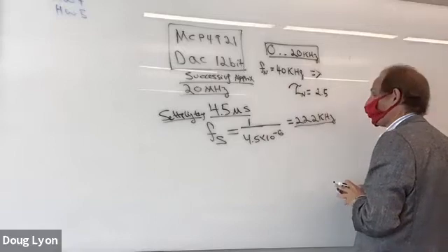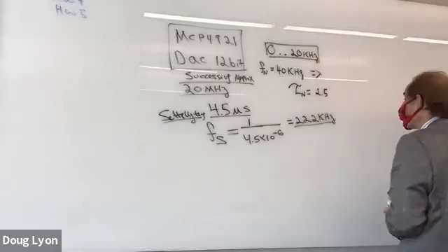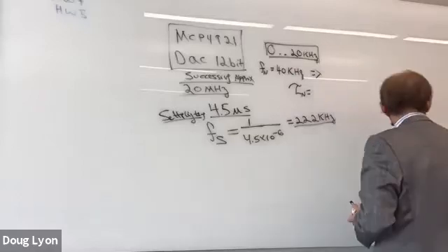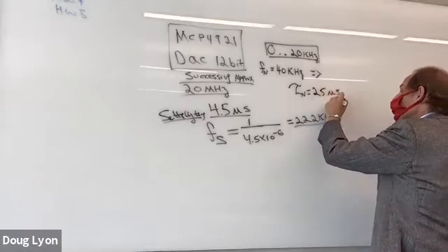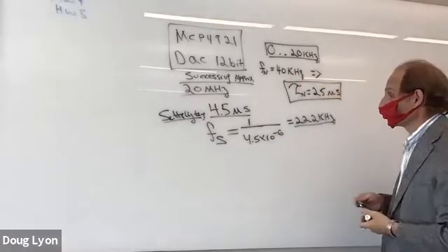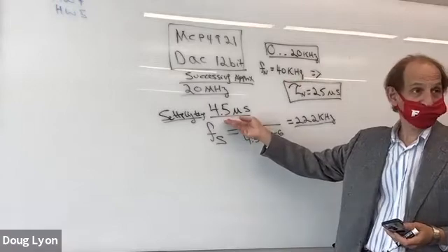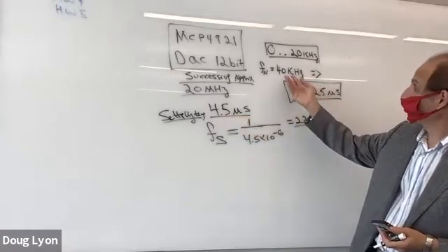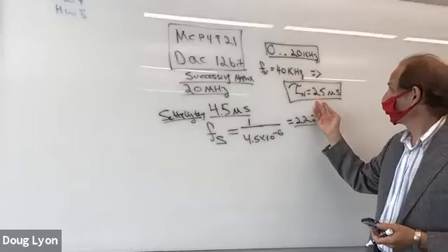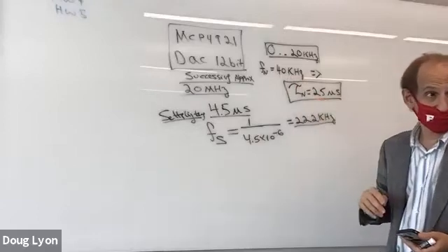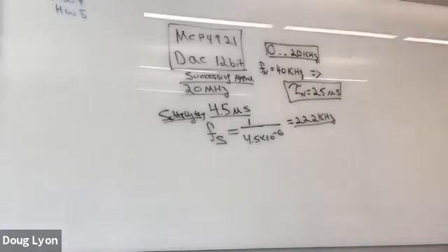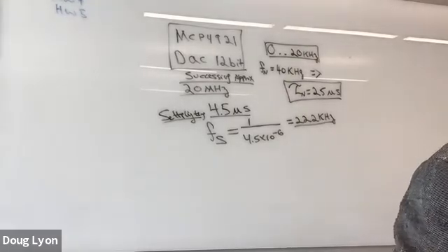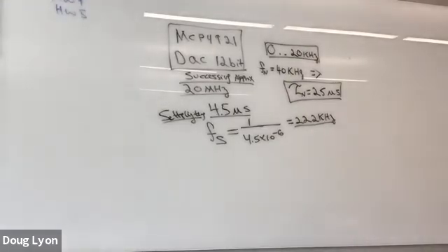It looks like 25 microseconds. So the DAC is capable of doing 4.5 microseconds, but even if you wanted to sample at 40 kilohertz, you'd only need 25 microseconds. And 25 microseconds is, well, perhaps an order of magnitude slower, and that kind of makes sense, than the 222 kilohertz in 4.5 microseconds.